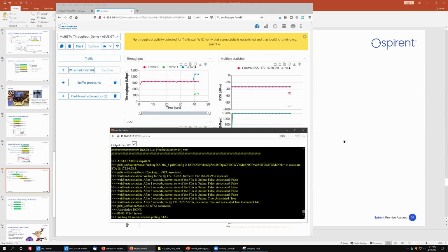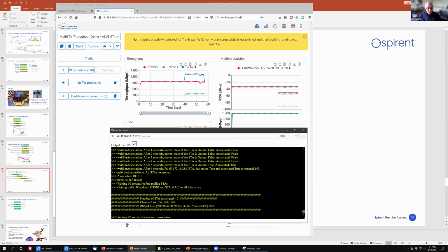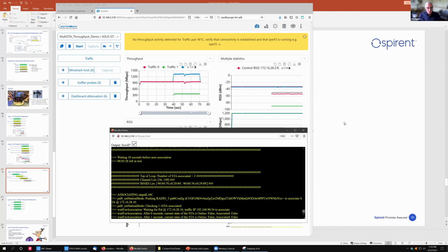Yeah. All right, so now we have our first instance of 2 radios, 2 fairly fast devices, and now each one got assigned to a different 5 gig radio. So one's assigned to channel 36, one's assigned to channel 149, and as a result, we have a nice bump in throughput up to 1.3. But we've seen this before. We saw this in the first case where initially we went up.